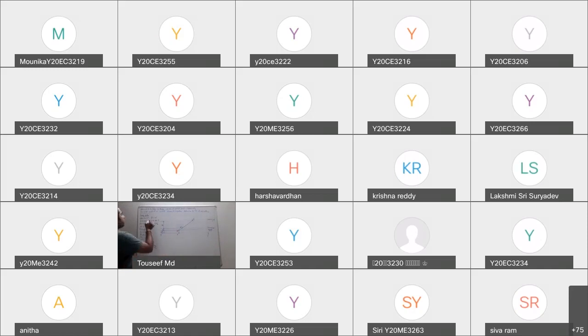From the given data, we already placed A and B, we obtained the front view and VT. The only thing remaining is phi equal to 40. Phi equal to 40 means inclination with respect to VP, which is always drawn below the XY line. So where is the point to draw the 40 degrees?